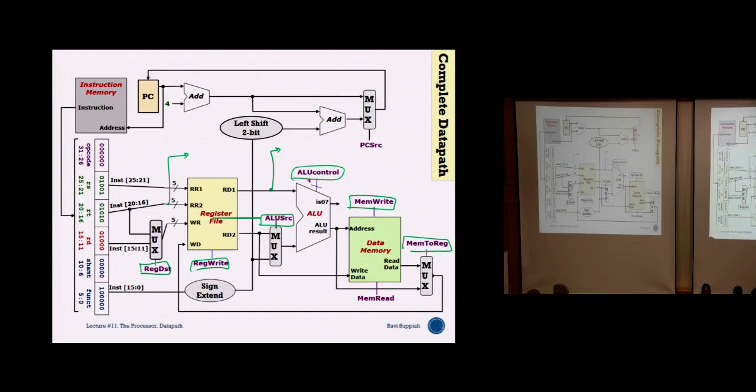So if it was 32-bit addresses, then you cannot load a byte. I think you're getting mixed up. The 32-bit address specifies one location. In one location, what is the data I have? If I say it's byte addressable, that means in one address I have 1 byte. That is why every time we increment the address by 4. But if I use load byte or store byte instruction, then I can also read and write in bytes. That is the lowest denomination you can use.